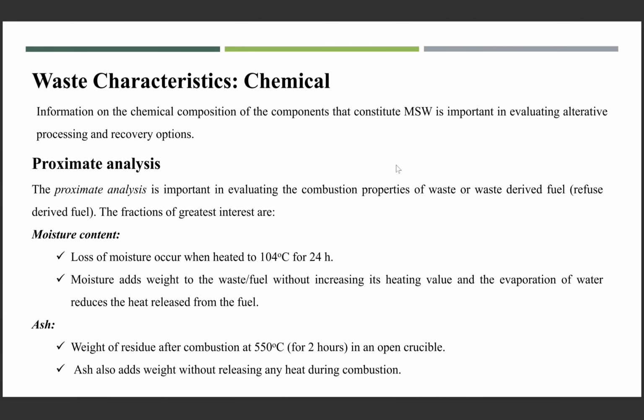So next are the chemical parameters. The first one is the proximate analysis. The proximate analysis consists of determining the moisture content, volatile matter content, and ash content.